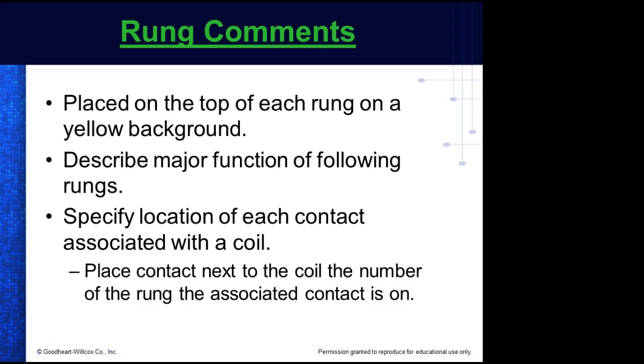Rung comments, we place rung comments on the top of the device. We can give a rung a comment, I'll show y'all that, or we can give a device a comment. The more comments or more information you put above each instruction, the easier it makes for you to remember what you were doing when you come back to it later, or if some other tech has to come in there and take care of your work.